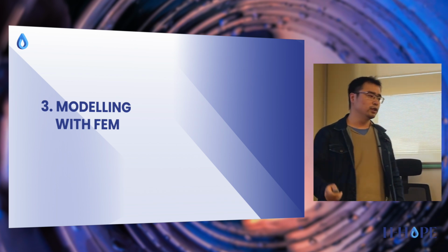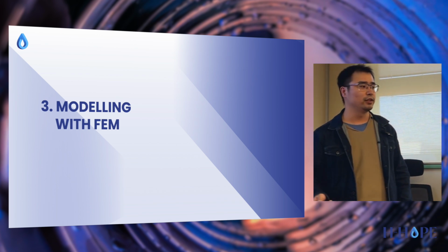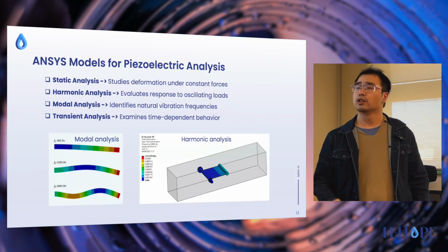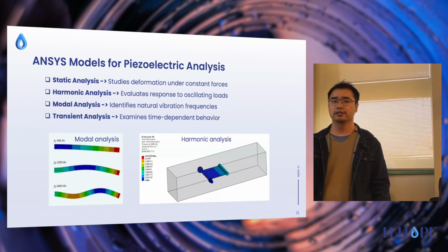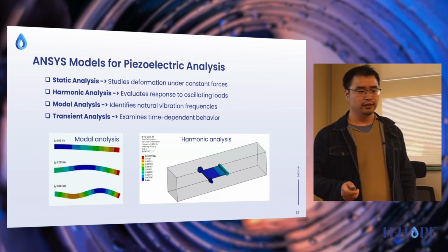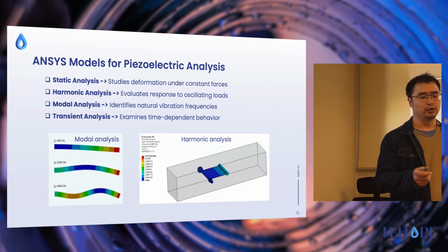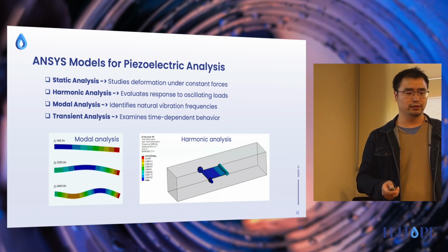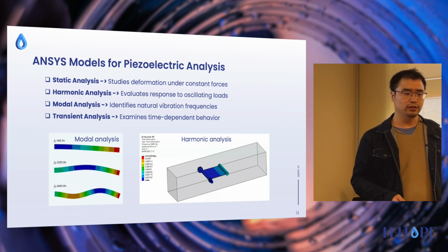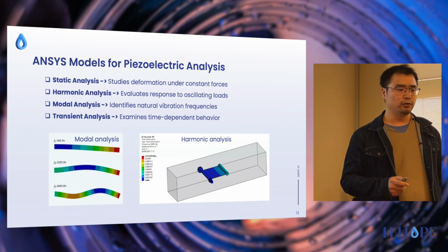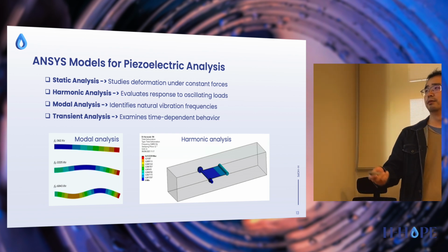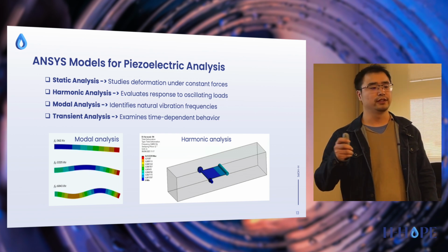Okay. Thanks, David. Let me talk about how to model the piezoelectric material with the finite element method. Here we just take ANSYS as the example. Using ANSYS, we can do static analysis to study the deformation under constant force, and we can do harmonic analysis to evaluate the response to an oscillating load. We can also do modal analysis to identify the natural frequency of the system.